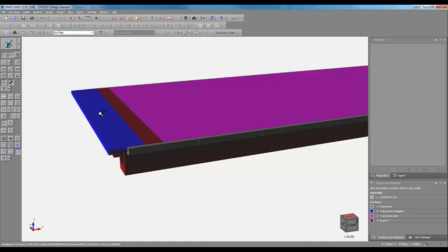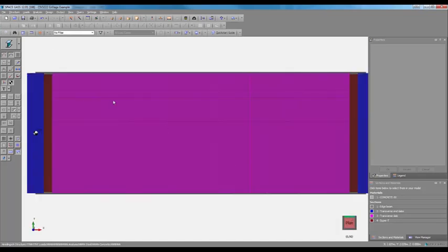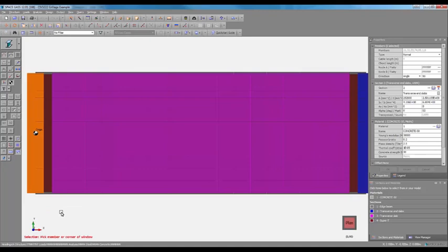So I'll move to plan view. So I'll select my transverse end slab. And I want to move this in the positive X direction by half its length, or its planned dimension, which is 1400. So I want to move it 700 millimeters in the positive x direction.